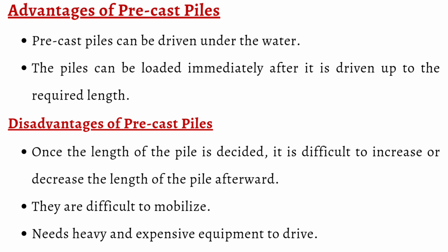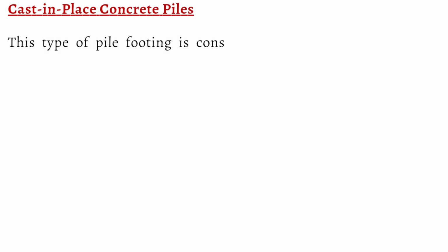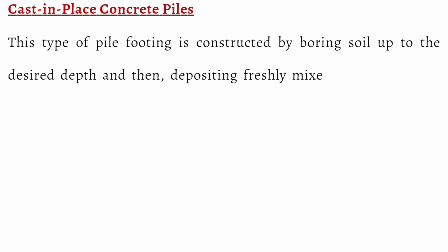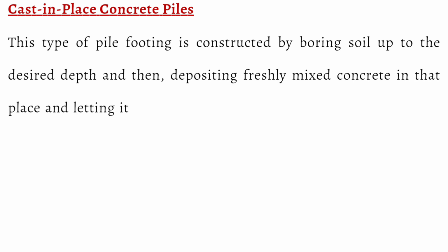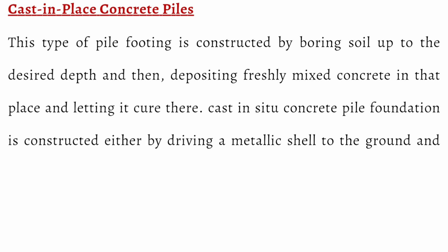Advantages of precast piles. It provides high resistance to chemical and biological attack. They are usually of high strength. To facilitate driving, a pipe may be installed along the center of the pile. If the piles are cast and ready to be driven before the installation phase is due, it can increase the pace of the work. The confinement of the reinforcement can be ensured. The quality of the pile can be controlled. If any fault is identified, it can be replaced before driving. Precast piles can be driven under the water. The piles can be loaded immediately after they are driven up to the required length.